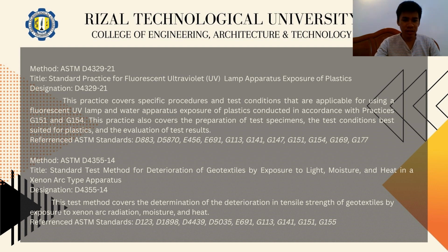And the last one is ASTM D4355, Standard test method for deterioration of geotextiles by exposure to light, moisture, and heat in a xenon arc type apparatus. This test method covers the determination of the deterioration in tensile strength of geotextile by exposure to xenon arc radiation, moisture, and heat. This method is intended to induce property changes associated with end-use conditions, including the effect of solar